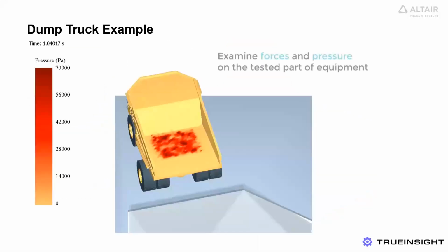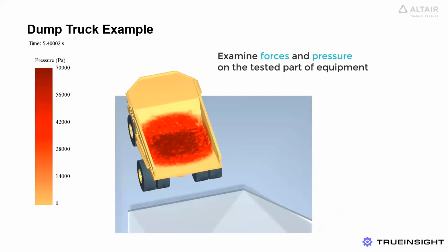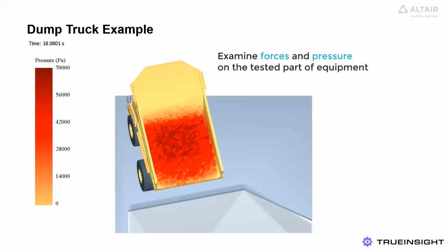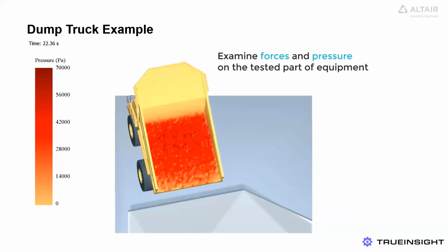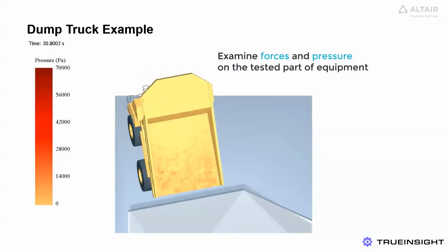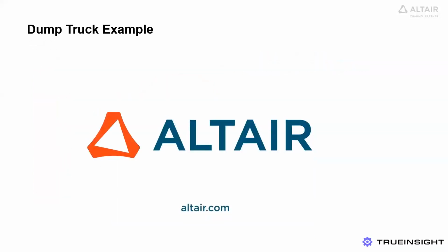You can also look at the forces and pressures that the geometry is experiencing to better understand the loads on the geometry or to analyze wear. And these loads can then be exported to a FEA program to structurally analyze the body and optimize the design.